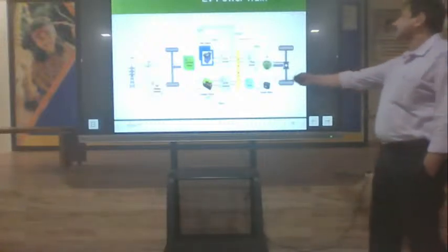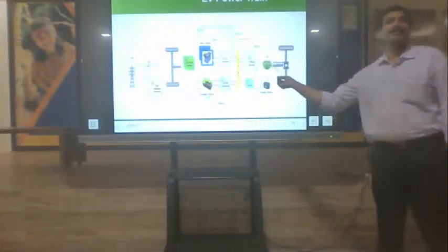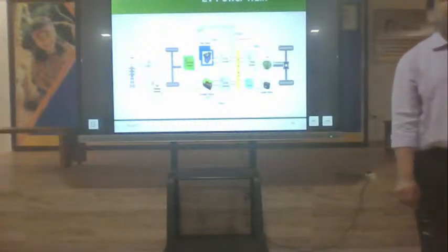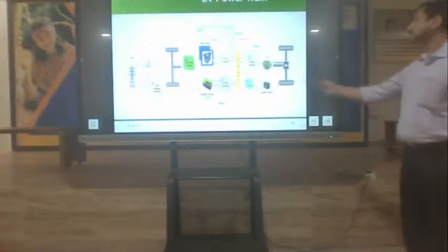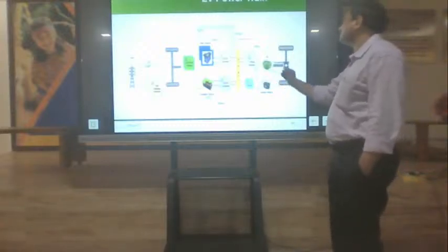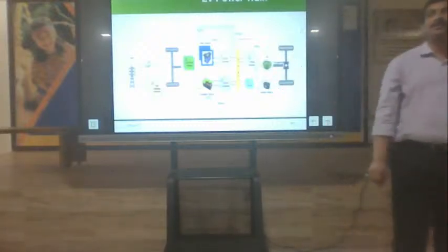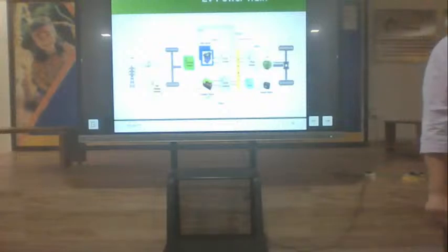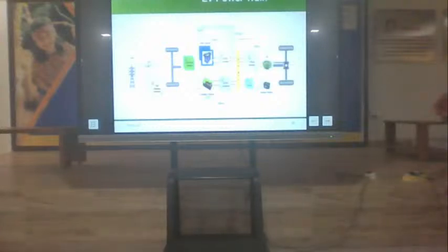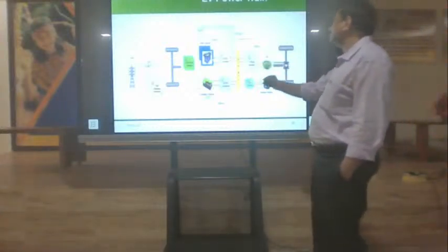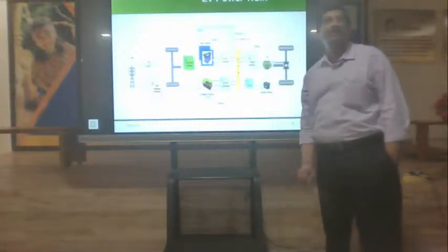See, the end thing that is driving the electric vehicle is an AC motor. Now, to drive this motor, the most efficient motor is a three-phase induction motor. So the main traction motor in the EV is still a three-phase induction motor. To generate the three-phase, you require a high voltage bus.